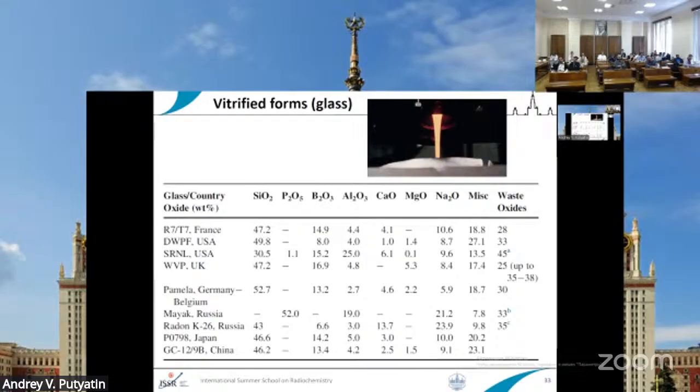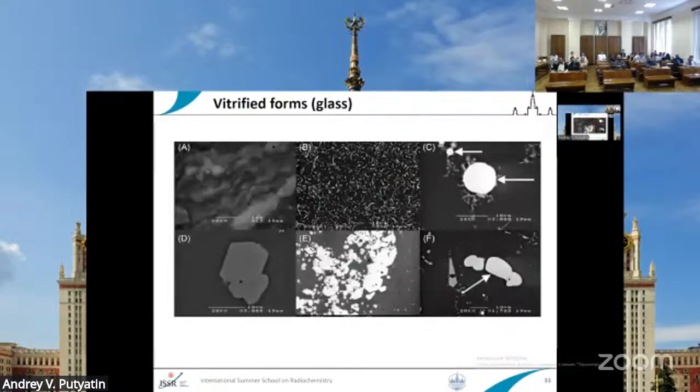The disadvantage of glass, that's why these elements cannot be placed in the glass, is the formation of crystalline phases inside the glass, and thus the formation of points with stress, and thus the glass becomes not very strong. It can be degraded to dust. It can have a lot of cracks.